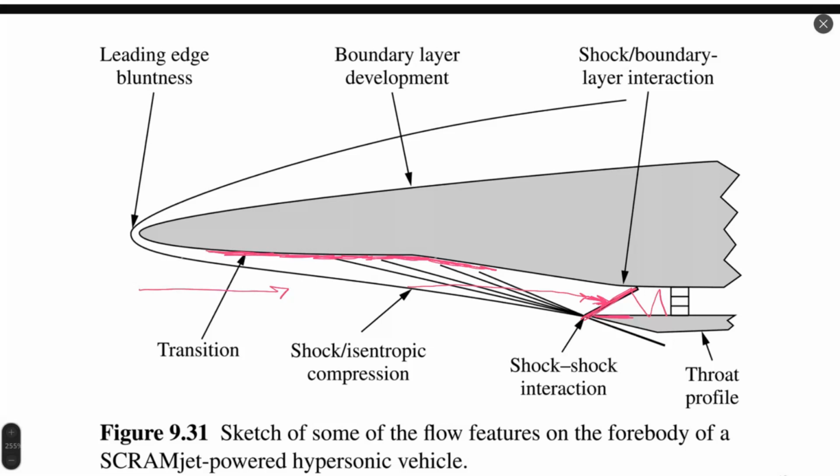It's not linear. It's not a simple curvature. Right? It's not just a line. It's sort of parabolic or hyperbolic, but cannot be expressed by a simple parabolic function. It is a complex function that is obtained by integration of Prandtl-Meyer flow point by point. Such works we can find in the literature, and the methodology to calculate such a profile is quite well known.